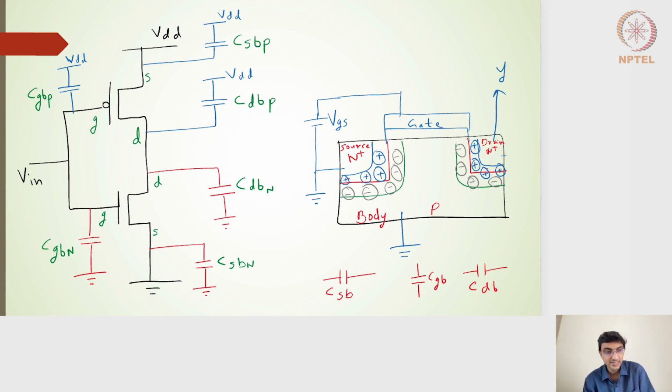Of course, it helps us in characterizing the delay of a circuit, especially the propagation delay falling and rising, which will help us characterize the delay of the circuits. The contamination delay falling and rising is also very important. If you remember the contaminated output, it should not get captured into the next set of circuits, especially when we are doing sequential circuits. We have to characterize the setup time and the hold time appropriately, such that this contaminated output doesn't get carried forward. So that is one thing.